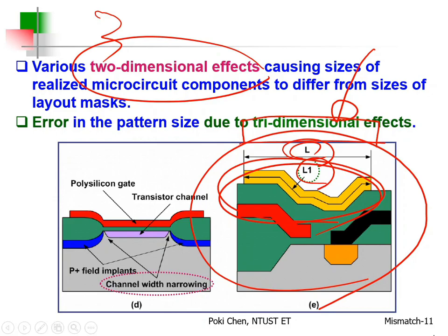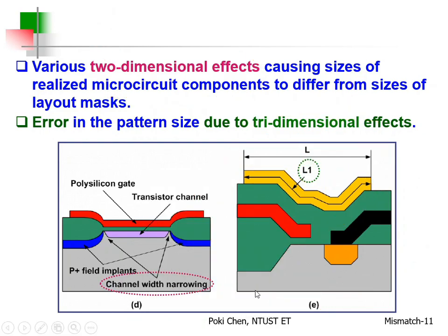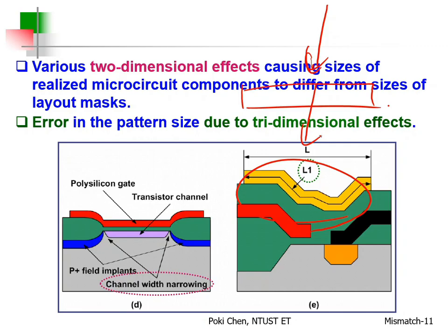So it means what? If you have 2 resistors to be matched, one just like this, and the other one is totally flat. Okay? The layout will be the same, because according to the layout, you only have bird view. Alright? But if you look at the cross-sectional view, you will know something is going wrong. Alright? So what does it mean? You need to make the overall environment exactly the same.